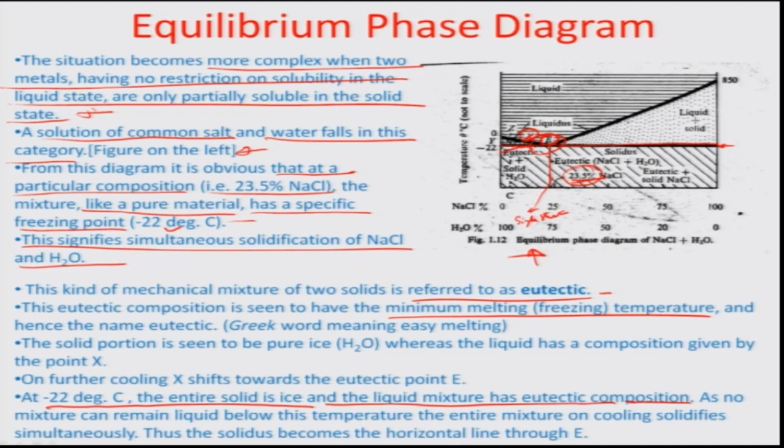For example, here you can see that you have over-concentrated ice in comparison to NaCl. So, some of the NaCl salt may be in some crystals, and some crystals may be completely devoid of the salt, and so you have a mixture of the eutectic at 23.5%, which is generally all over, but then there are certain other solid water or ice, just ice, which has no salt as well.